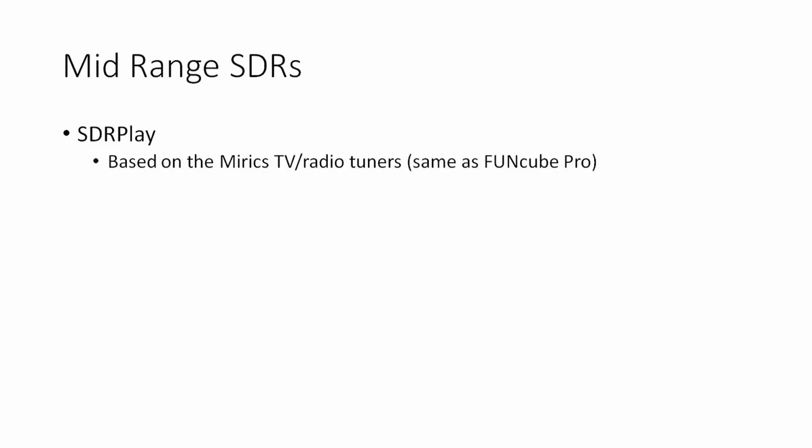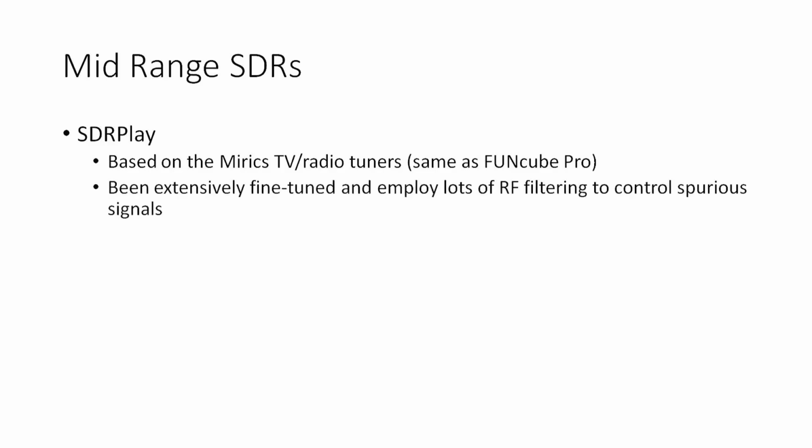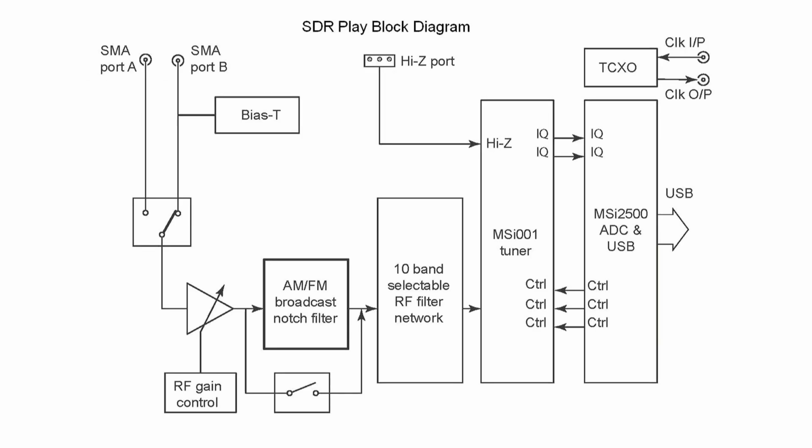It's based on the little Mirics TV radio tuners. That was the same as Howard used in the FunCube dongle. But they've done a hell of a lot of work. At least one of the engineers, if not 2 of the engineers from SDRplay, used to work for Mirics, so they know the chip very well, and they've done a great job of extracting about as much as you can possibly get out of that Mirics chip. So it works very well.